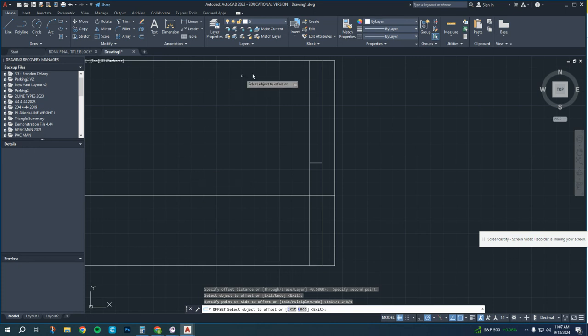Hit enter. Again, I'm going to do another offset up here, and you only have to click it once because I've already done one, so I'm in the right direction. Again, it's 2, minus symbol, 3/4 to type in the 2 3/4. And we're going to use a trim option here. Trim allows you to either click on or drag through things that you want to delete in between 2 endpoints of the line. So I can click here and here. So now I have 2 equal parts here and 3 equal parts on the right.